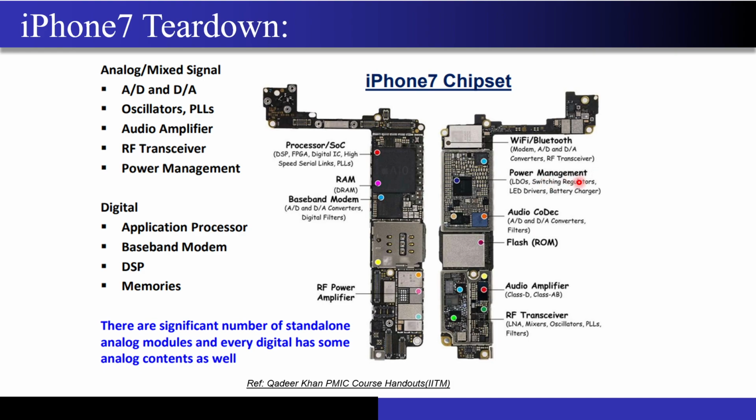So you have the power management chip over here, and these small white or whitish yellow patches that you're seeing over here are all the passive components, that is the capacitors and resistors that you were not able to put on the chip. Why were you not able to put them on the chip? Because they occupy a lot of area. You don't want to pay a foundry such a high cost just to fabricate the passives, right? So that's why you have many passives present around the chip, since this would have taken a lot of area. That's why they have been taken off the chip.